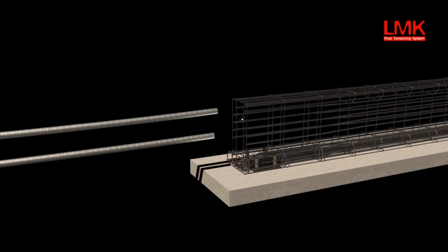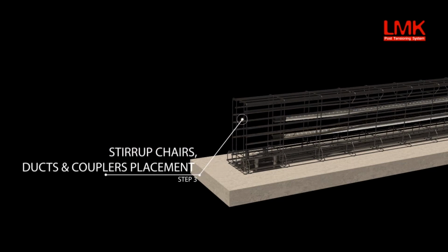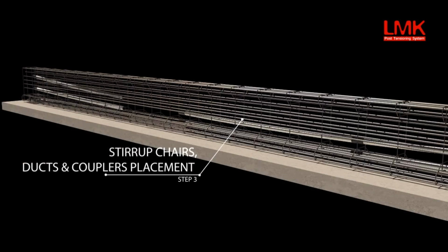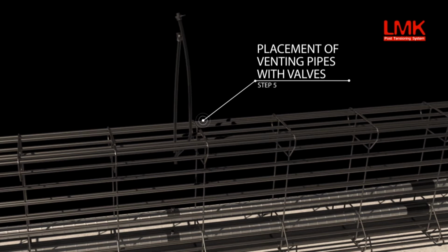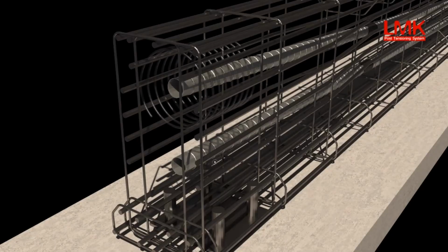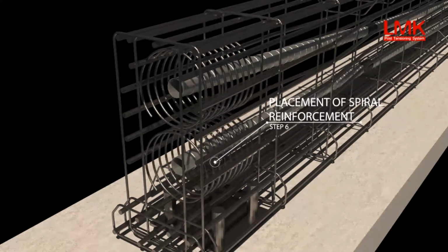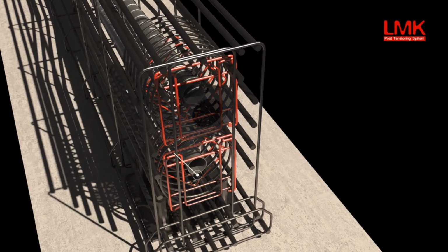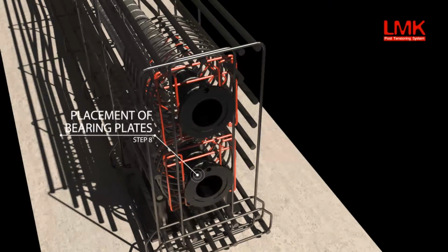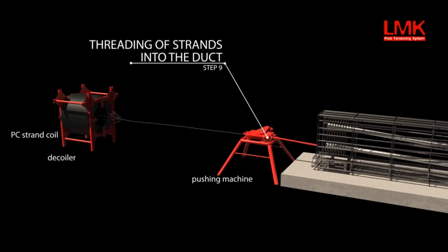In the design of a reinforced concrete beam subject to bending, it is accepted that the concrete in the tensile zone is cracked, and that all the tensile resistance is provided by the reinforcement. The stress that may be permitted in the reinforcement is limited by the need to keep the cracks in the concrete to acceptable width under working conditions. Thus, there is no advantage to be gained from the use of the very high-strength steels which are available. The design is therefore uneconomic in two respects. The weight includes useless concrete in the tensile zone, and the economic use of steel resources is not possible.